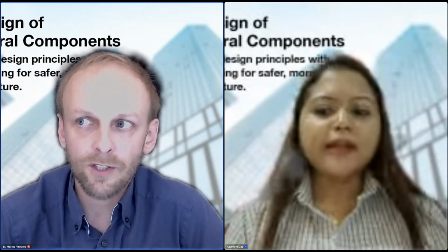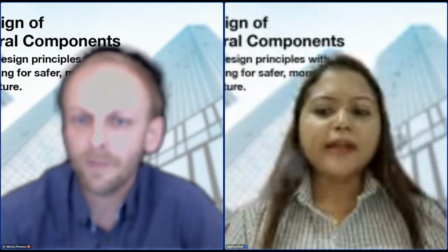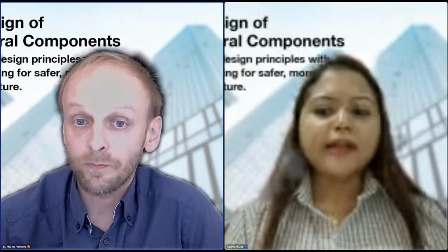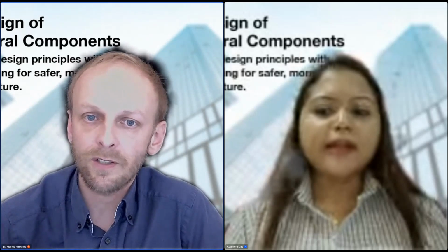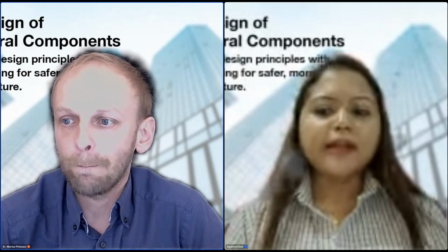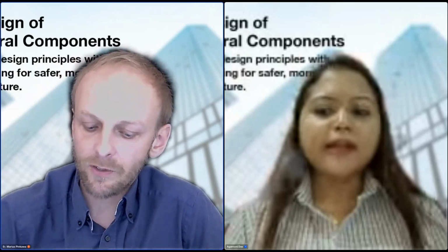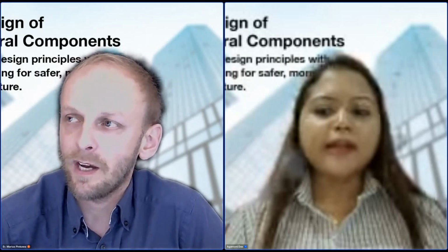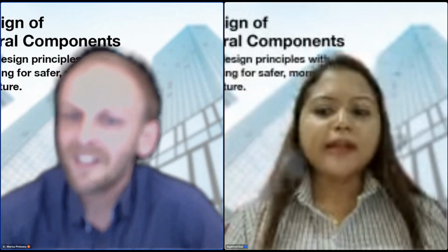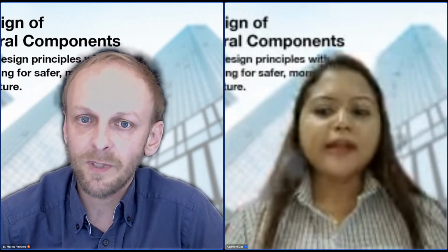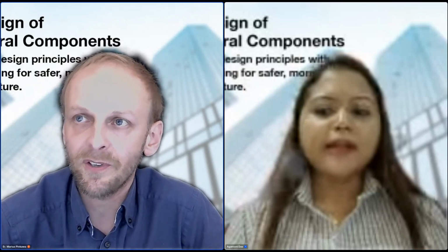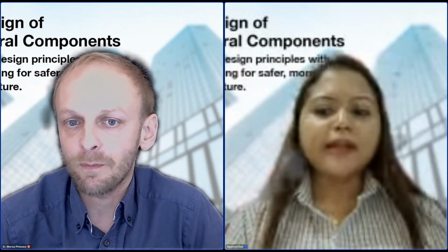So in general, seismic demands will be very large if the period of the component matches the relevant period of the supporting structure. If I understood the question right, the other aspect was, do I need a coupled model? If there is resonance between the supporting and secondary structures, a coupled model is more important.